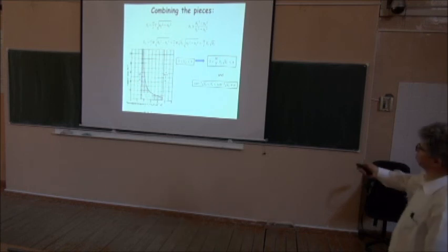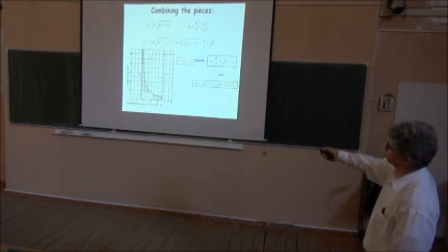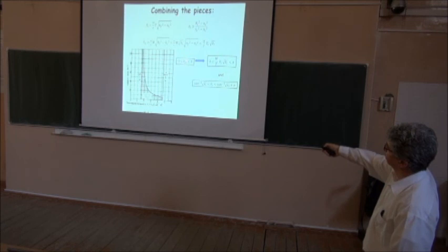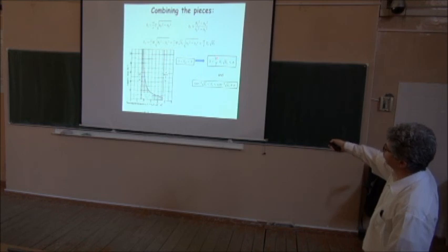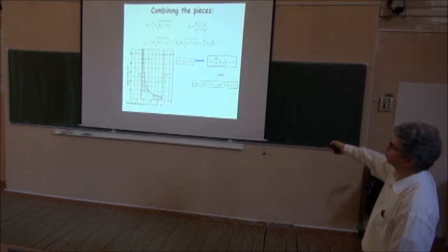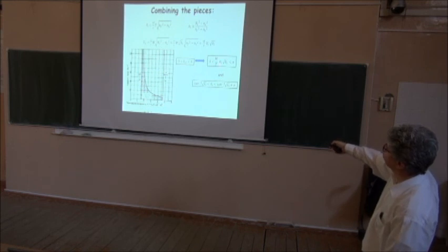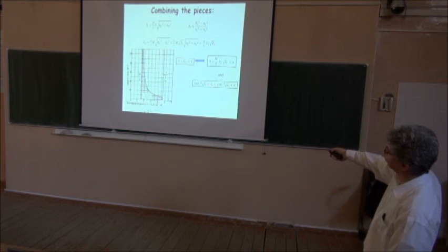So now, from the previous slide, we know that this V2, for single mode operation, should be between 0 and pi, but I can relate V2 in terms of the constant that I have here. So I know now what aspect ratio range I can afford to have single mode operation, and it's given there. And I know also what is the range of V1 that I need for single mode operation. That was the result of the previous slide, and I copied it here. That depends on the symmetry factor. So the V1 is in this region, and I can bring that limit to this region there.